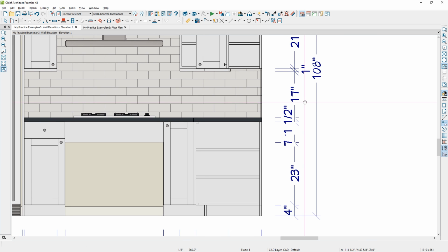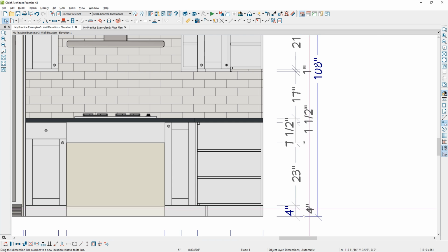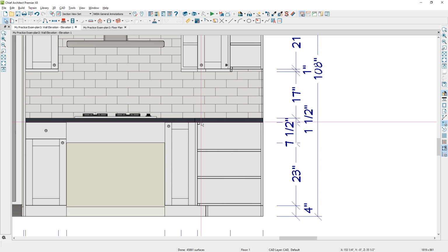Pull, zoom down. Again, click on the dimension, figure out what we've got going on. We've got top of countertop and then the cook range. Let's go ahead and pull the 1/2 inch, 1.5 inches out for the countertop, and then our toe kick. So all of these dimensions seem important that we have on there. Again, if we've cut a section and we don't want to see the cabinet box, I'm going to use our cross box tool. Come into the corner, come out here and click over the top of that box.